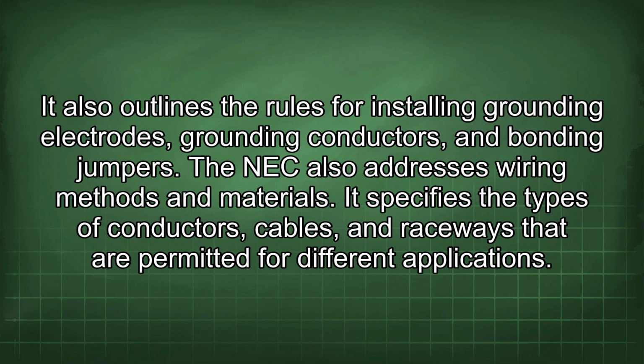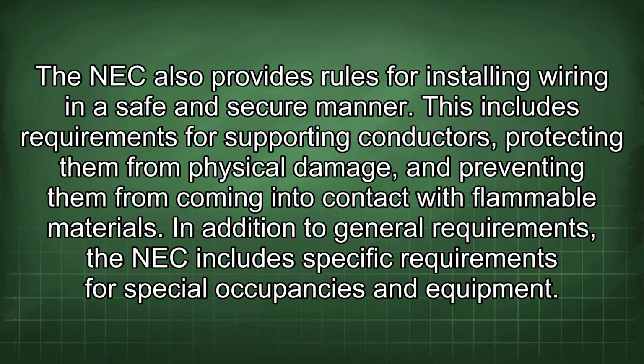The NEC also addresses wiring methods and materials. It specifies the types of conductors, cables, and raceways that are permitted for different applications. The NEC also provides rules for installing wiring in a safe and secure manner. This includes requirements for supporting conductors, protecting them from physical damage, and preventing them from coming into contact with flammable materials.